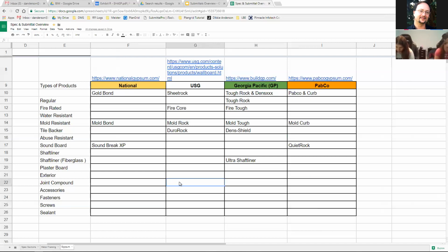of taping, topping, all-purpose. There is another one that we will use depending on how projects go, and they will refer to it as hot mud. And they usually will refer to hot mud by the number of minutes. Okay, so you have a 90-minute hot mud, you have a 60-minute hot mud, you have a 30-minute hot mud, and I think there's even a 10-minute hot mud.